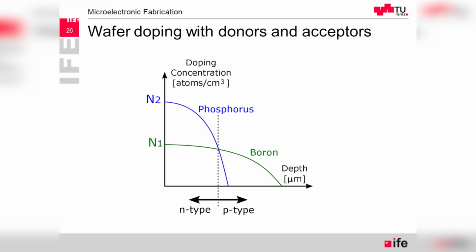So what we can see here is phosphorus and boron, which are different types of dopants. One is acceptor, one is donor. And what we are doing now, in this step where we are adding the N-well implant, so doping a big island for the transistor, but inside it we are going to add P and N type implants for the drain and source and for the bulk.